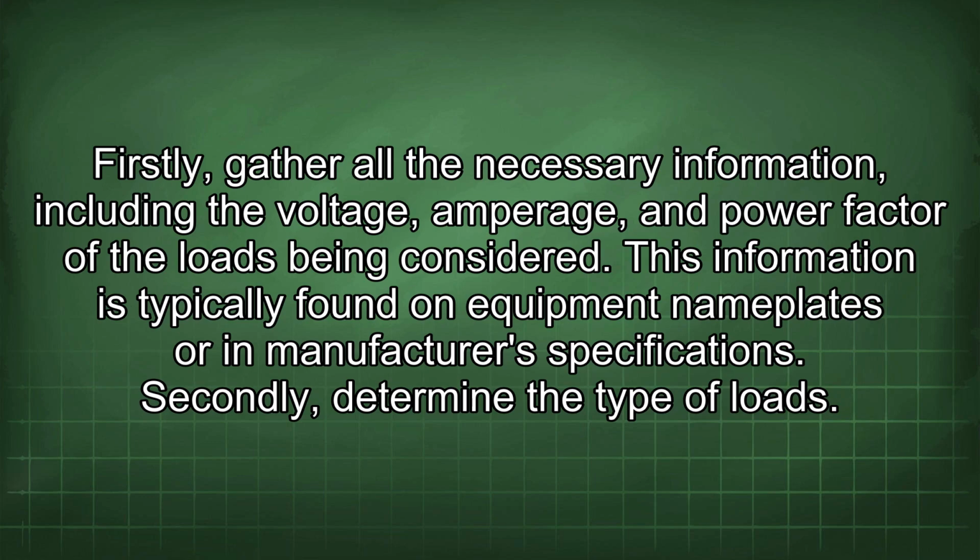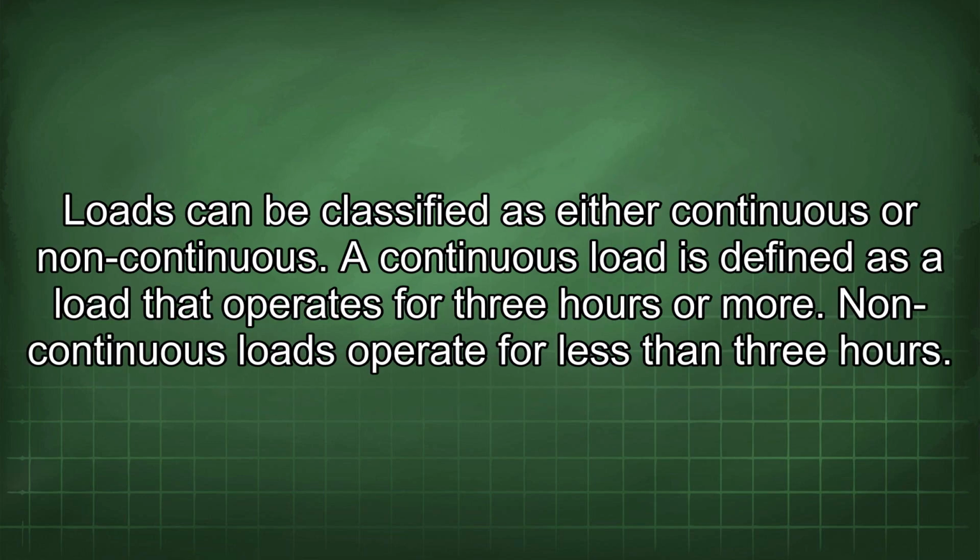Secondly, determine the type of loads. Loads can be classified as either continuous or non-continuous. A continuous load is defined as a load that operates for 3 hours or more. Non-continuous loads operate for less than 3 hours.